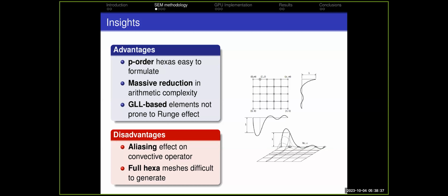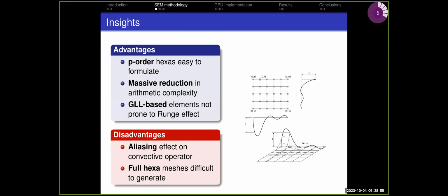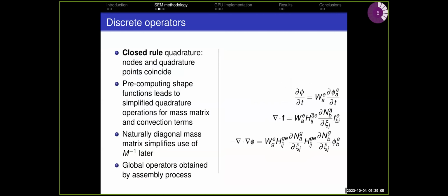order. Right now, how we deal with this is by using either Gmsh or ANSA, which have certain higher order full hexa capabilities. And as shown in the slide before, we end up with meshes similar to these, where the elements are a bit ugly, but because of the way our code is built, it can handle this, let's say, ugly discretization. So coming to what's actually the meat of SOD2D, which are the operators in the Navier-Stokes equations.